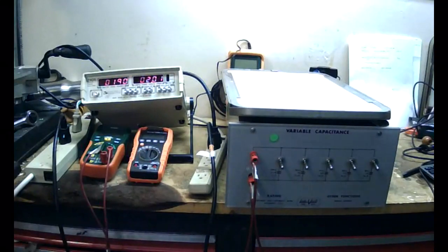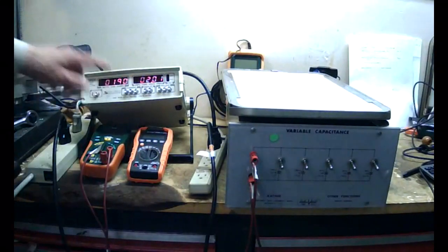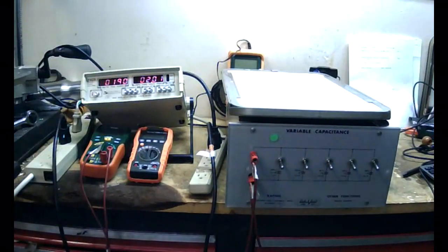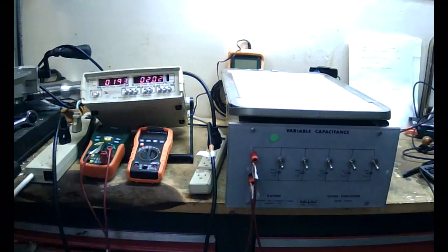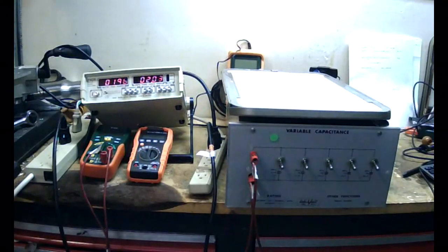Here's the drill press. Real power on the left. On day 5, we were drawing 216 watts. Today it is drawing 190. That's mostly because the voltage varies in this workshop, just like it varies everywhere on the power system. You just don't usually see it. But it's drawing 190 watts today. Our calculations were with 216, so we're going to see a little bit of difference. But we'll do the reactive power calculations using what we took today.